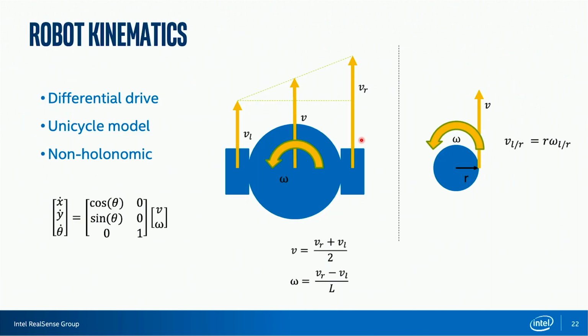I'd like to talk about the robot itself. It's a differential drive with a caster wheel, and we are assuming point contacts to arrive at these simple relations. What I want to highlight here, on the one hand, are the intrinsic parameters of the odometry calibration, which is the wheel radius, as well as the distance between the two wheels, basically the baseline. And with this relation, one arrives at a unicycle model that can be used for the control.